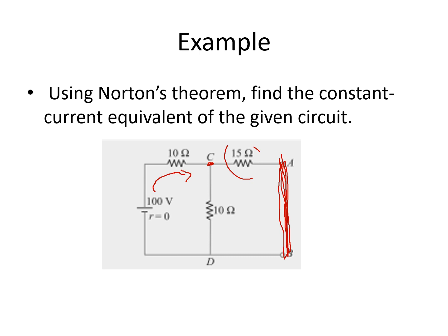We have already short circuited your A and B, and then we will be getting your equivalent resistance. Okay, so what is your equivalent resistance here? REQ is equivalent to 15. As you can see here, they are in parallel. So 15 parallel 10, and the parallel combination of these two is in series with your 10 ohm resistor, so we have here plus 10.